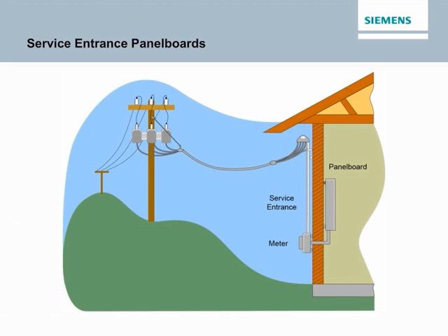According to NEC Article 408, panel boards used as service entrance equipment must be approved and labeled as such. Siemens offers panel boards that are factory labeled as suitable for service entrance equipment when NEC requirements are met.